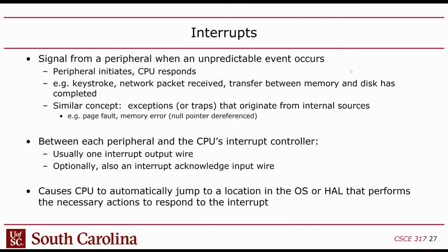Okay, now switching topics again, let's talk about interrupts. I mentioned programmed I/O was a process that can only be initiated by the CPU. The CPU can initiate communication with any of its peripherals through programmed I/O by loading or storing, which is equivalent to reading or writing special register values on the peripherals. The problem is, what happens if a peripheral needs to initiate communication with the CPU? It can't do that through programmed I/O.